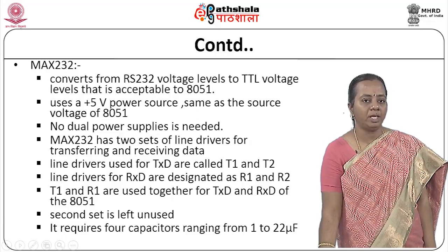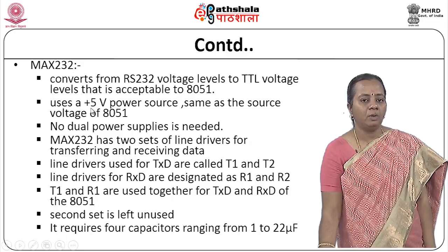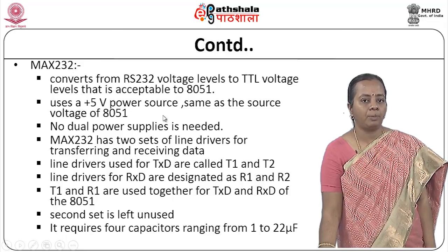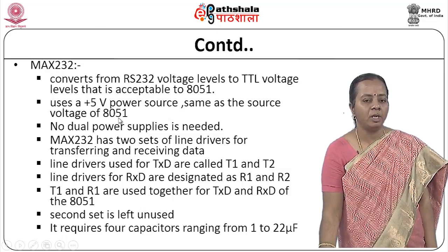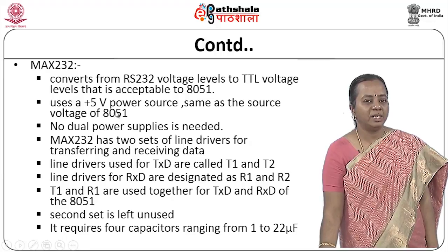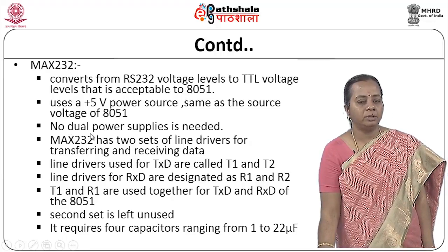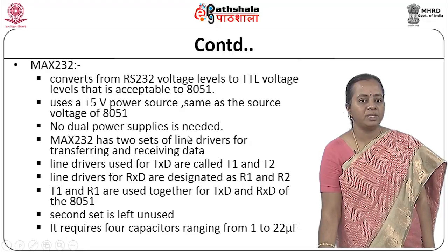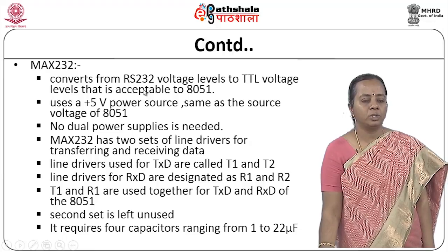MAX 232, which is otherwise called a line driver, uses a plus 5 volt power supply, same as the source voltage required for 8051. So there is no need to go for a separate power supply for this converter, and no dual power supplies are needed to connect your 8051 as well as your MAX 232 chips.